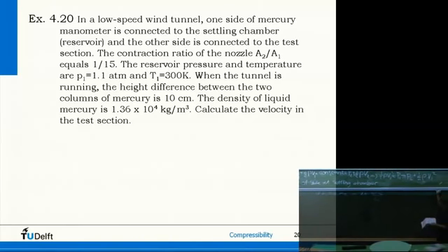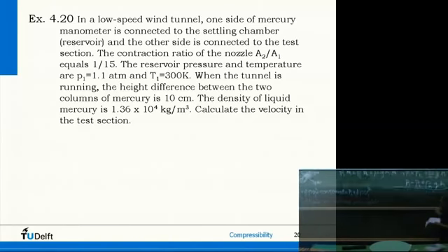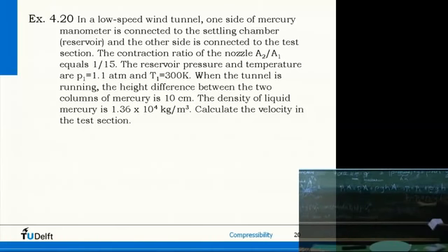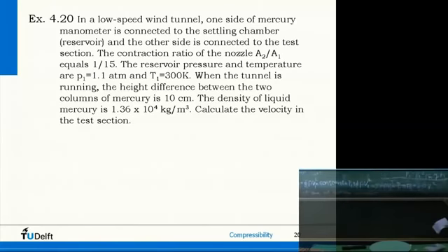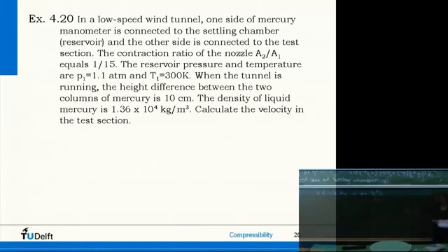And then we have it. So the steps we went through: the manometer gives us the pressure difference. Bernoulli relates the pressure difference to speed squared. Density from location 1, because we have pressures and temperatures there, from the equation of state. And then finally we use the continuity equation, V1 A1 is V2 A2.